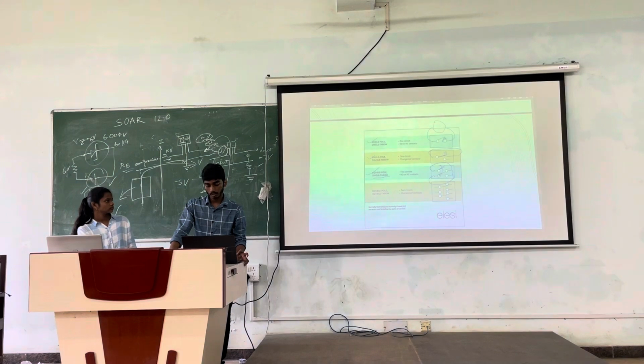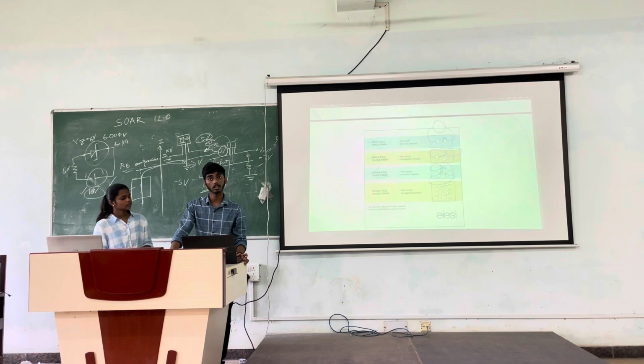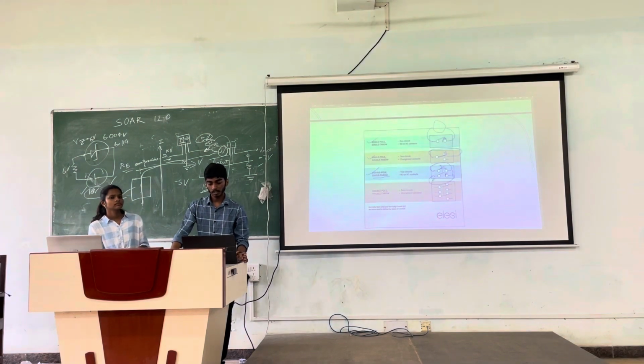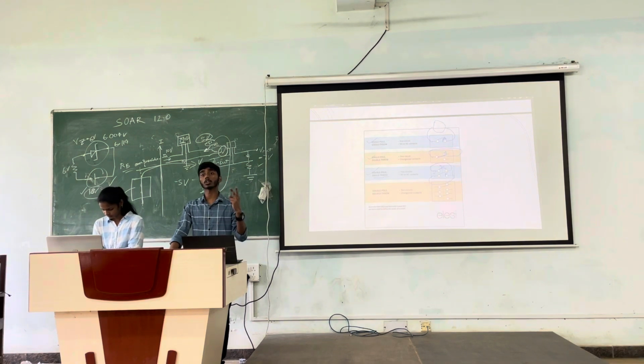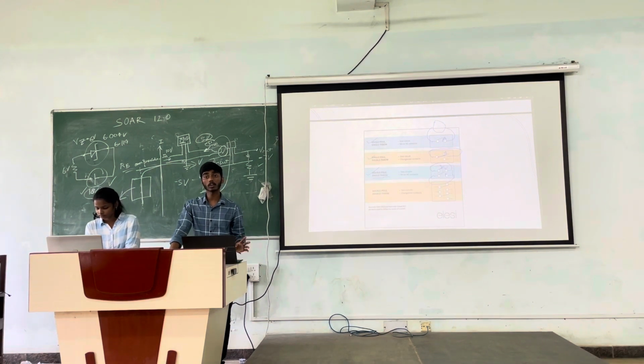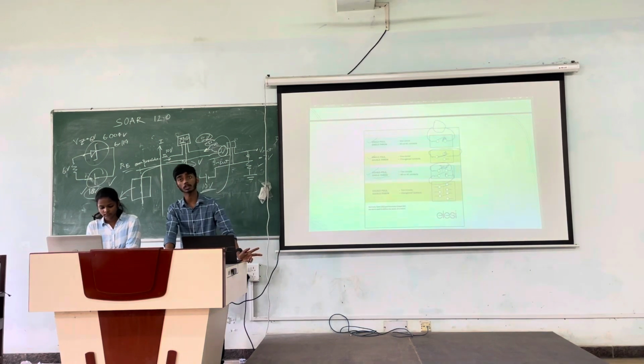Okay, so this toggle is not connected to any of the terminals. So we are still having a single contact point here. Similarly, a single contact point here for this toggle. So we have double pole, as the name says. So we can control two circuits with one contact point. That's why the name is DPST, double pole single throw.